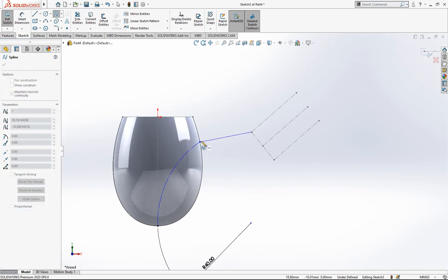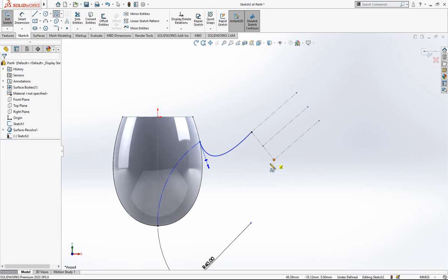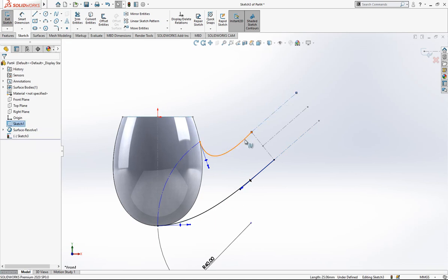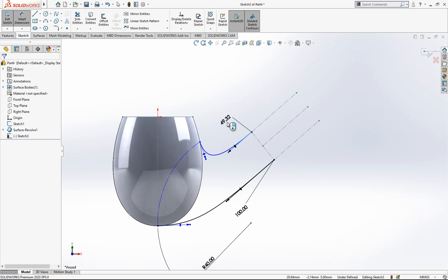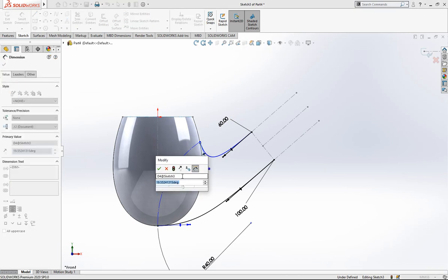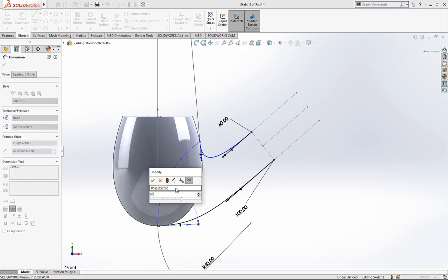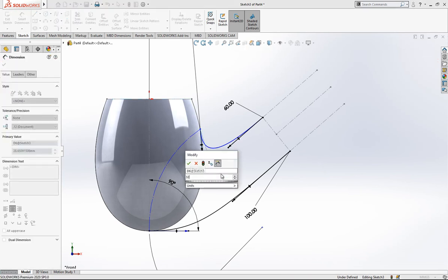After this operation, we create the first spline here and the second spline here. Firstly, I will make the splines tangent here, this point, and the tangency value here 100, and this point just 60, and then the values will be here for angle 5 degrees, and here now I gave 90. And then the tangency value of this point, 32.